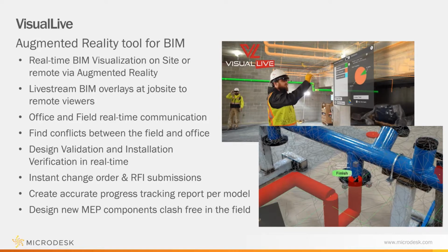Now, the really cool part of this, that a lot of people are like, wait a minute, I don't understand how it can actually save that much, is the idea that this can avoid laser scanning costs by up to 60%. How this is beneficial is that a lot of our clients, a lot of people working in the field, are taking scan data. They're utilizing that for a few reasons. One of those reasons is for doing checkups. So I need to get an accurate location of where everything is, maybe not so much for an as-built, but just to make sure that, when we said this is where all of our core drills, penetrations and hangers are going to be, I can coordinate what they did in the field with what we told them to do.